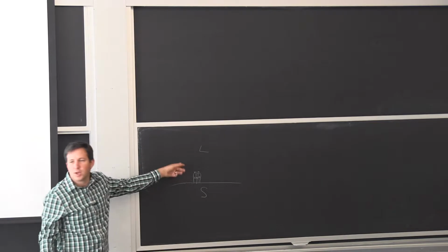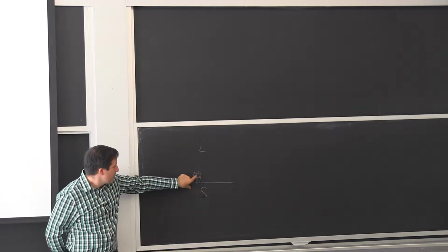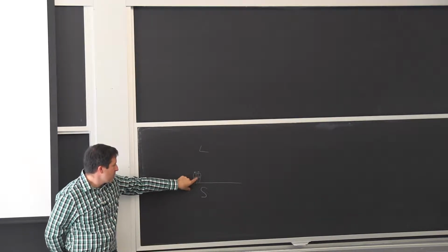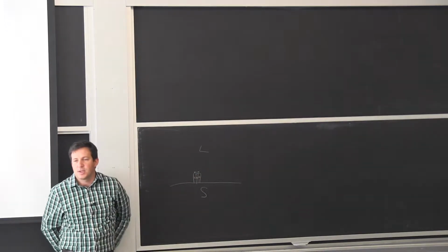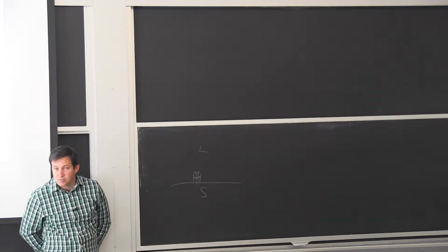I'm just moving the two elements in opposite directions. So one phase is going to become silicon depleted, and the one next to it is going to have more silicon. That way you get a very fine grain size right from casting.